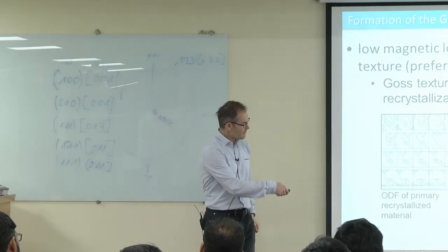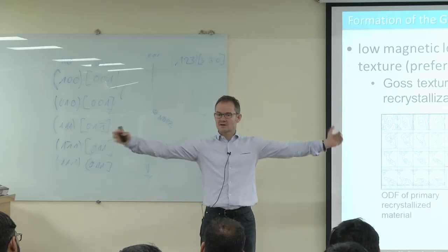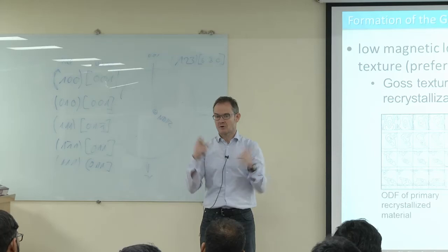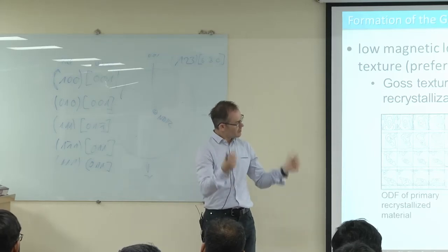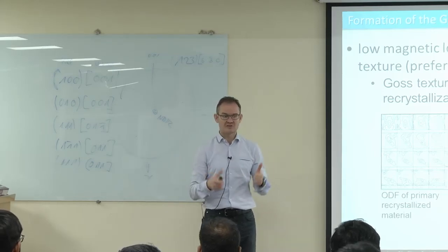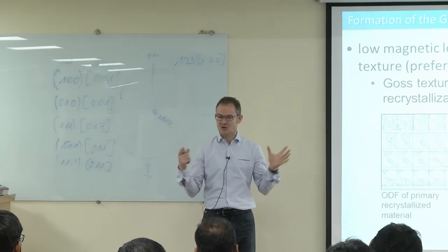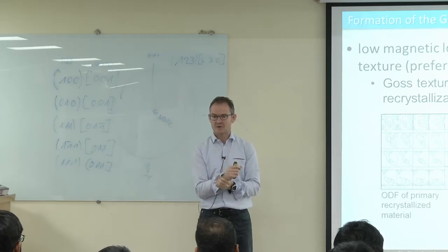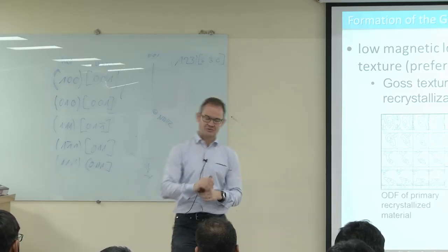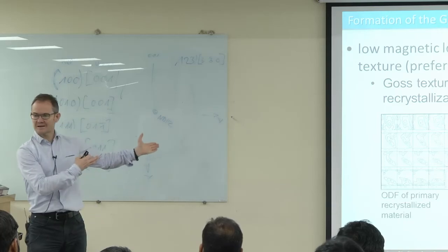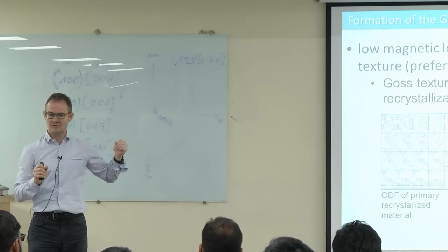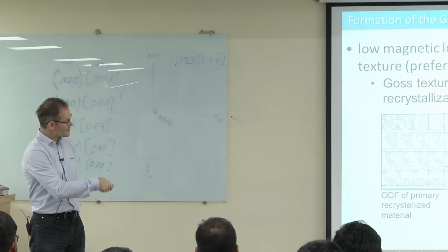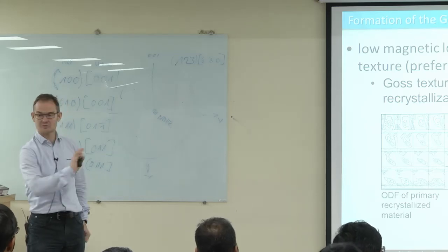And one Gauss grain consumes during its growth 1 million of other grains. So it's only 1 out of 1 million, or in some special high quality steels, it's even 1 out of 10 million grains which decides to grow. And miraculously, this is all Gauss oriented. Why is that? That's quite a miracle, and it's also quite a nice display of why it's important to care for textures. You want to make sure that these textures are right in order to make these textures perfect.